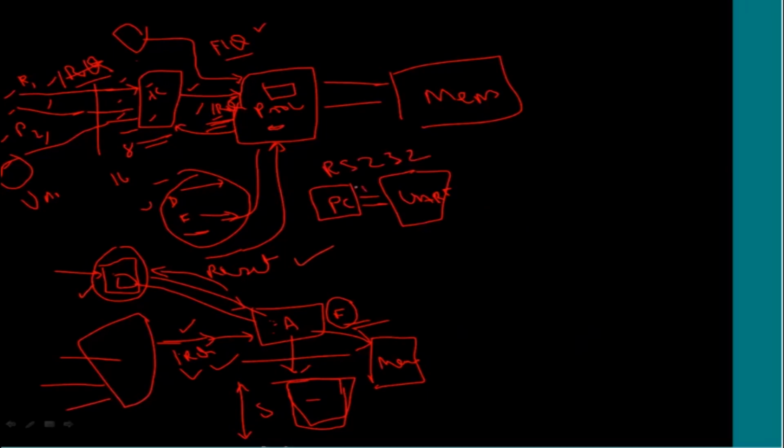So there are two signals. From the UART perspective, TXD is sending data to the PC, and RXD is the input to the UART. This is connected to the interrupt controller, and that in turn is connected to the ARM processor through the IRQ input.